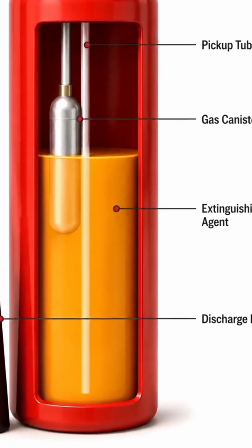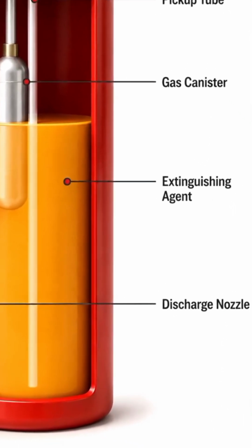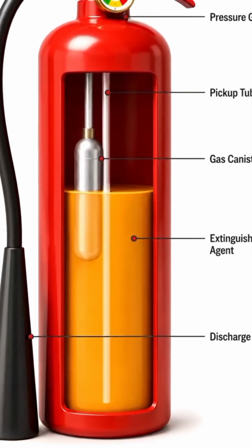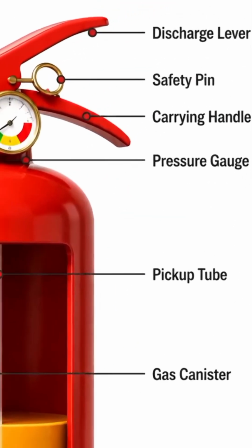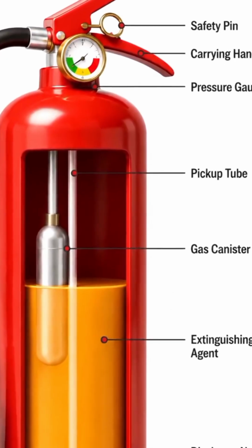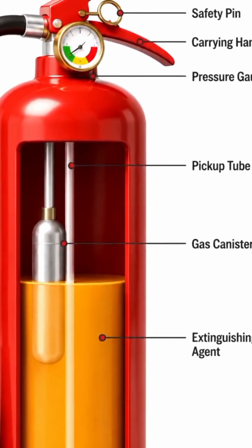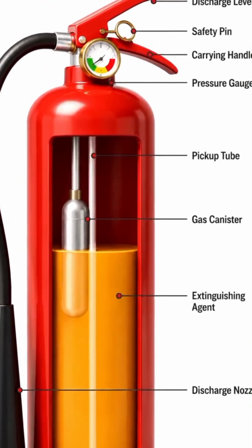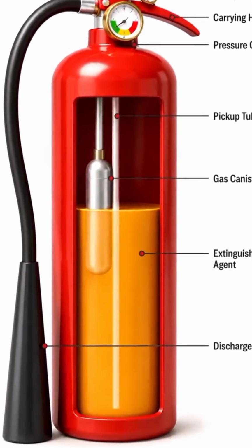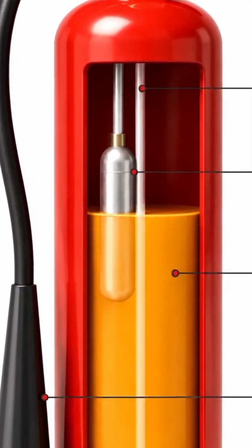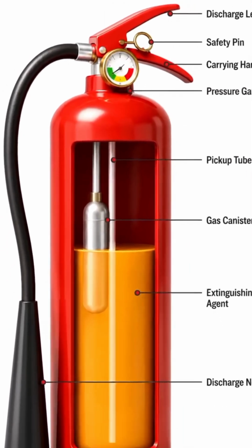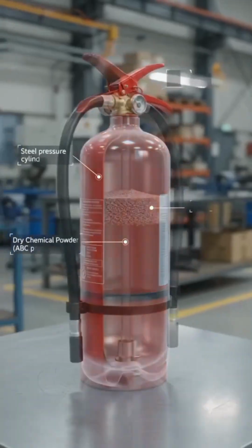This ensures that the extinguishing agent covers the fuel and cuts off its contact with oxygen or chemically interrupts the chain reaction. The third step is to squeeze the operating lever. Squeezing the lever depresses a valve stem inside the head mechanism, opening the passage from the siphon tube to the discharge hose. The internal pressure immediately drives the extinguishing agent up the tube, through the hose, and out of the nozzle. To maintain a continuous flow, the lever must be held down firmly.